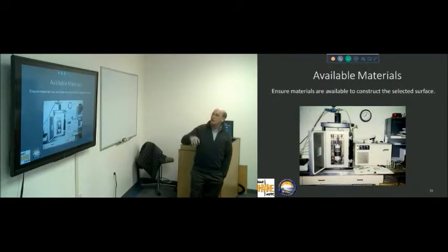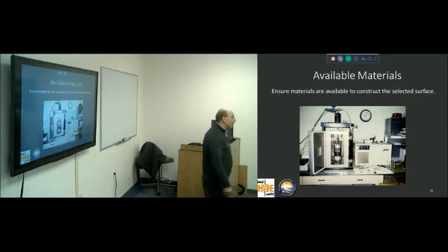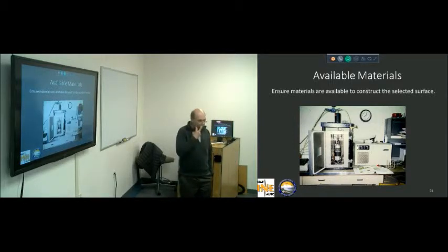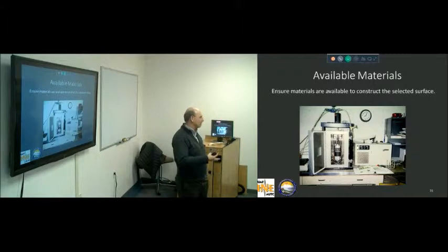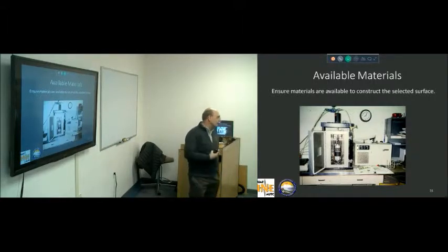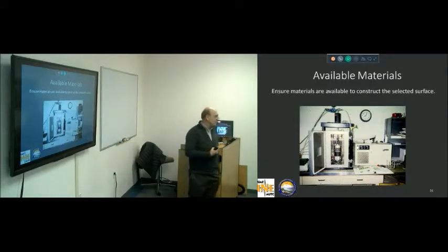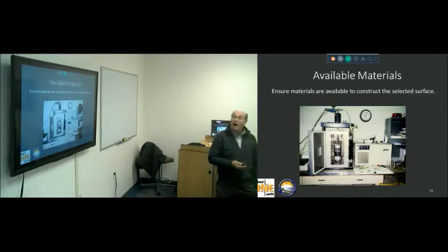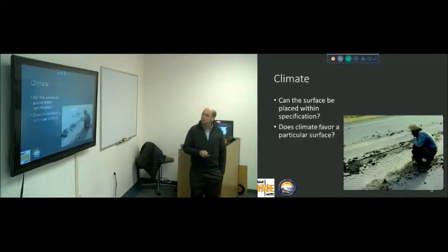Okay? One of the things we want to talk about again is available materials. Make sure the materials are available to construct whatever surface you're going to make. I've seen a number of instances where a designer just assumes that it's going to be there, and it's really not there. A little bit of upfront work going out there and making sure the material's there. And if it's not there, what are you going to have to do to make it work, or are you going to have to haul material in, import material in to make that work? Those are all decisions that need to be made up front, not after the fact, when it's going to cost a lot more to resolve the problem.